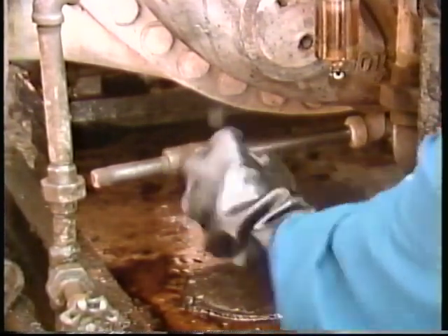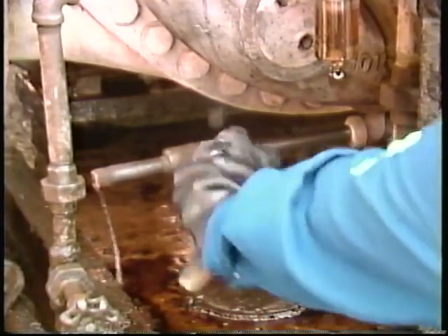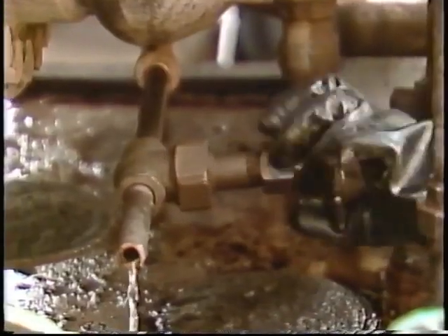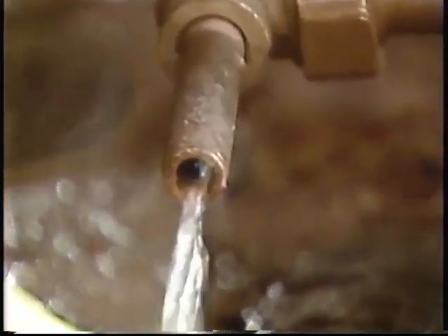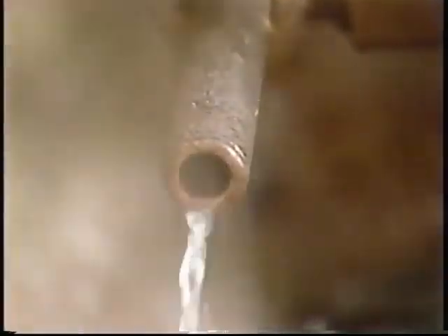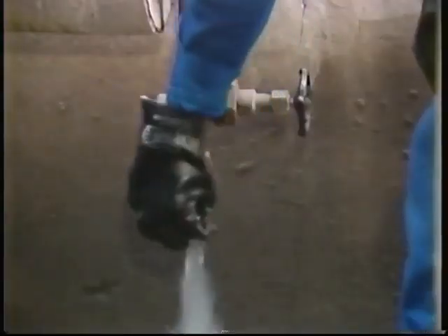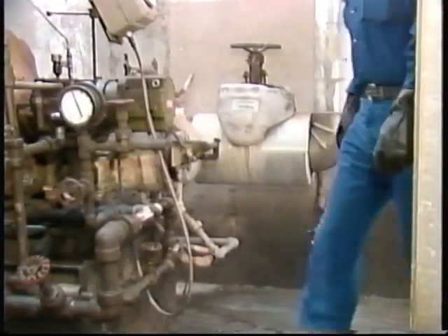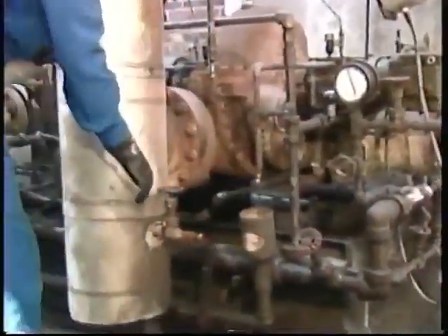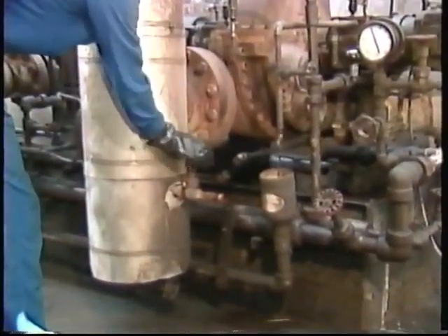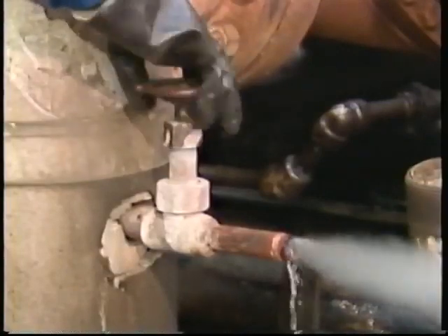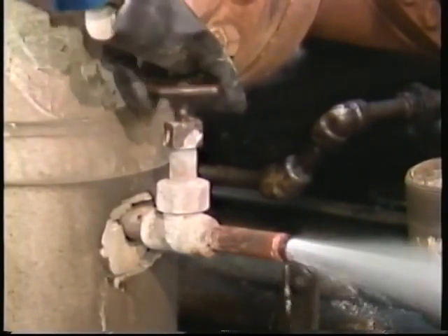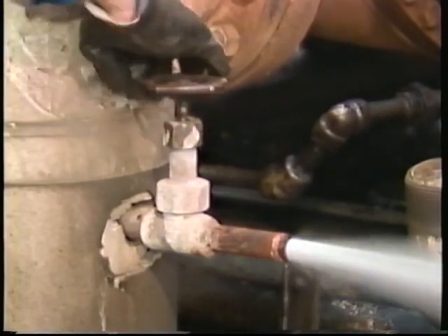Condensate, the moisture that's produced when steam cools and condenses in the piping, can cause serious damage if not removed from the turbine. Drops of moisture that strike the high-velocity blades can chip or pit the blading. So, before steam is admitted and the turbine is started, drain valves are used to remove condensate from the casing and steam chest, as well as from the inlet and outlet piping. The drains and their valves are located at points in the steam flow path where moisture is likely to collect.